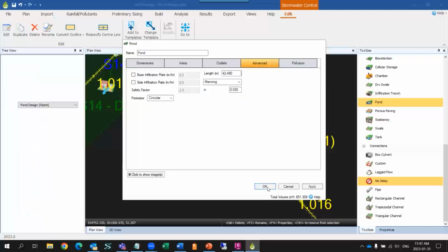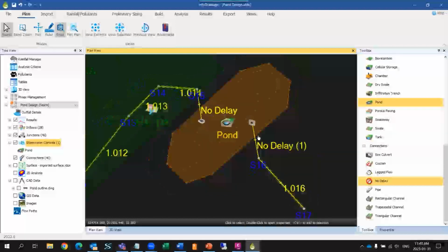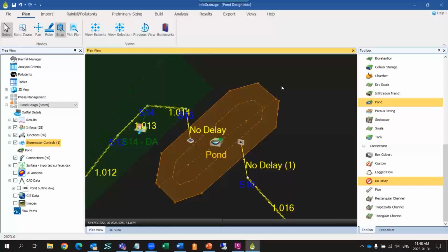And I can say, okay. So those two conditions look fine. What if we're going to hit a 1 in 100-year storm, and you definitely don't want the pond to be flooding? So how can we avoid that situation? So maybe I could provide a weir or some opening here. We can tell, okay, when it reaches this water level, right, close to the top water level, let that weir be in action and water flows through the opening or things like that, right?